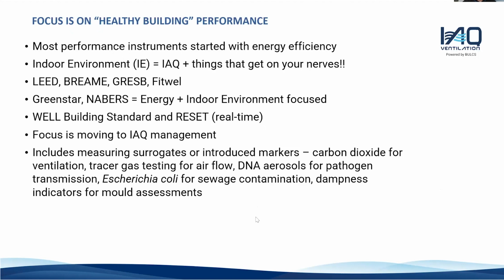So the focus is of course on healthy building performance. Most performance instruments start with energy efficiency in Australia, such as NABERS rating, or indoor environments or IEQs, like LEED, Fitwel, and green building. And of course, Green Star and NABERS again would be energy and indoor environmental focus: light, sound, your six parameters, PM2.5, temperature, humidity, etc. And WELL buildings will mainly focus on four predominant pathways out of the nine that they have.